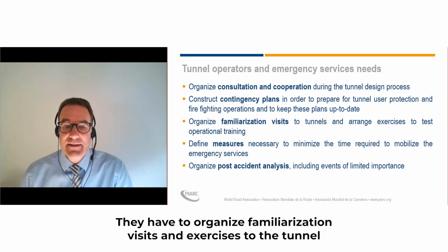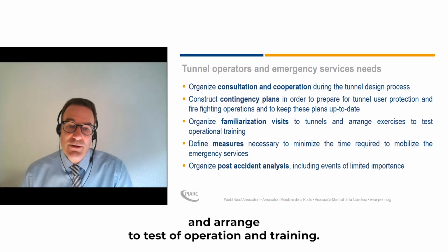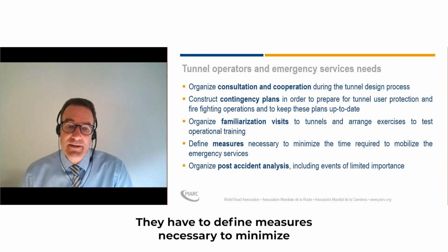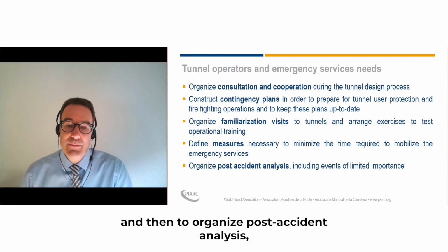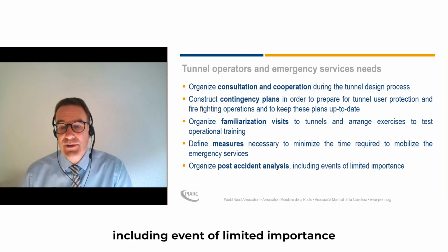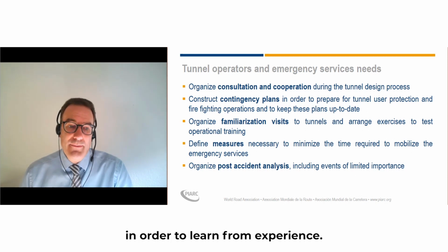They have to organize familiarization visits and exercises to the tunnel and arrange the test of operational training. They have to define measures necessary to minimize the time required to mobilize the emergency services, and they have to organize post-accident analysis, including events of limited importance, in order to learn from experience.